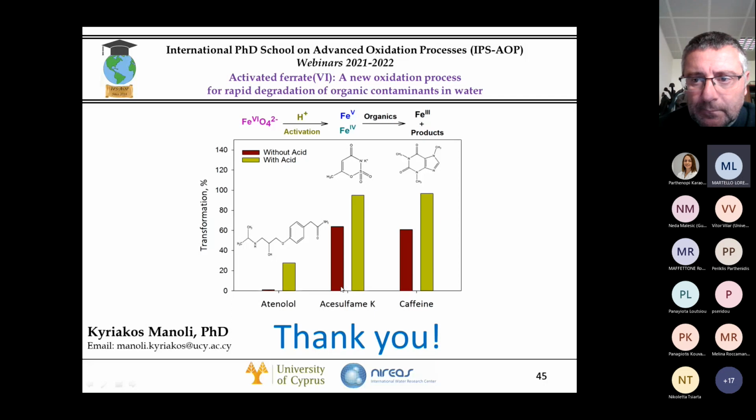Actually, depending on the regulations, Fe(III), because at water treatment pH, Fe(III) will be particulate, so it can be removed in different ways. There are people investigating magnetic separation or simple coagulation or simple settling or filtration, depending on whether the amount of Fe(VI) that is used is high, and then this is a requirement.